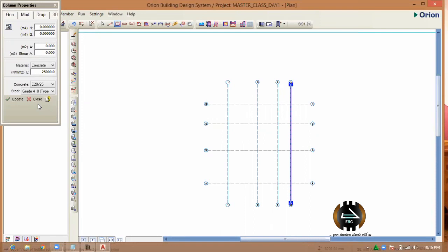Why? Because we're looking at the strength of the reinforcement that was provided. Because when you're calculating, your software and your manual is telling you 410 reinforcement times 4. So it's already carrying that 410 FY steel strength for 4 bars. And what you're buying and using in your project is around 300, 380 at most. If you're very lucky, 390. I'm not sure. I've not seen 400. I've not seen 400 for a very long time.